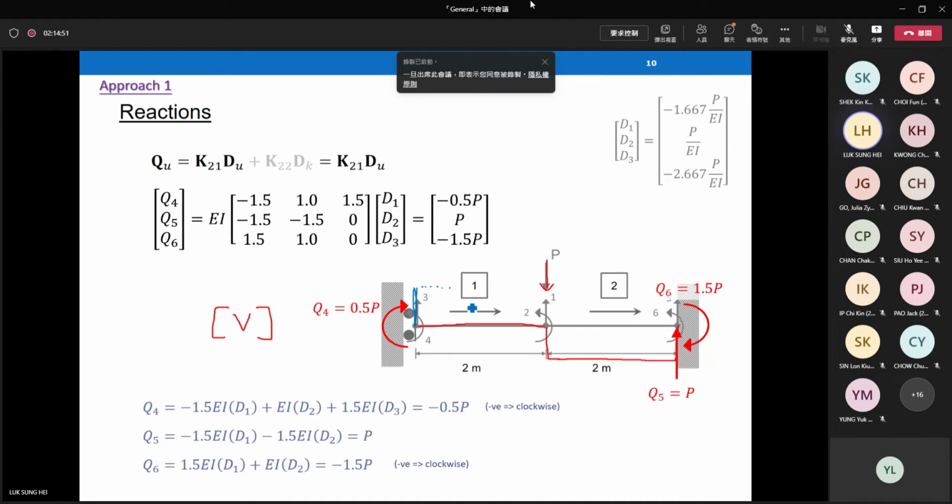The first span. The graphical method gives us one property. The shear force is equal to the slope in our moment diagram. The slope in our moment diagram is equal to the shear force at that point.